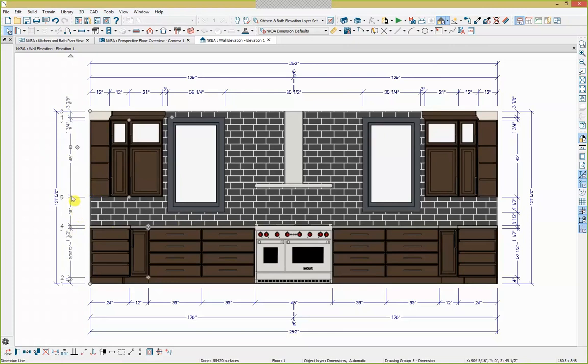If you want to add dimensions, you can click on that string. There's an extra diamond handle. Just click and drag that into the plan, and you see that the program adds a dimension into our plan. So really fast to create these dimensions in the software, and then you could further notate it using the CAD tools and the text tools if you would need to.